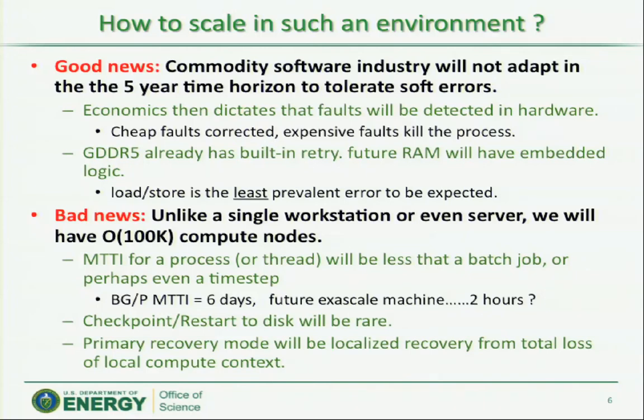But things like retry and all that, they're actually going to be pushing that down into the memory system. So you're going to start getting logic in the memory to do that before the chip even sees it. There's an extra layer of silicon underneath the DRAMs now. They're going to start putting more logic in there, and that's embarrassingly parallel and very low power.